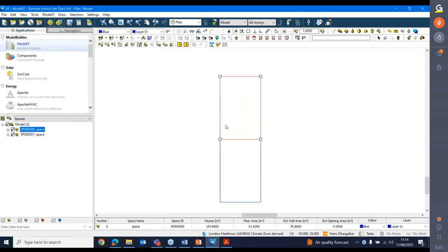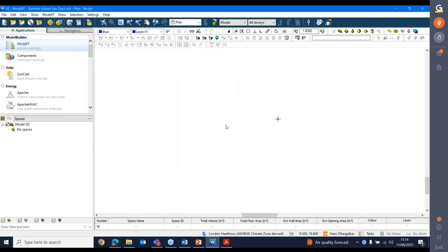So there is an option if you attach a drawing to move the drawing. Here you can move the DXF file, but we'd recommend getting them lined up in CAD first and exporting them as DXFs. So you export your drawing from CAD as a DXF file, either AutoCAD or ArchiCAD or whatever tool you're using. You can bring that into IES and do it in a plan view. That's a very simple example. Okay, I'm going to show you a more realistic example.